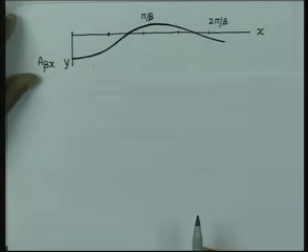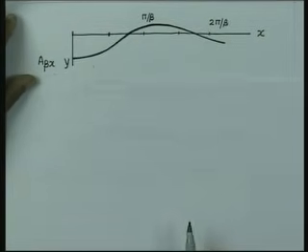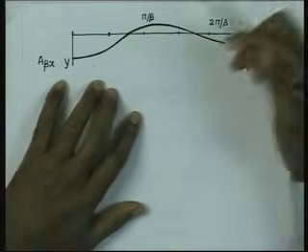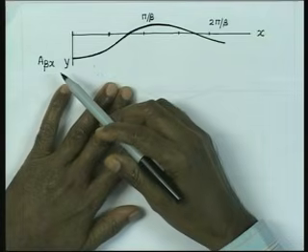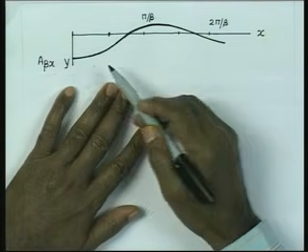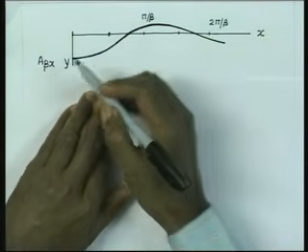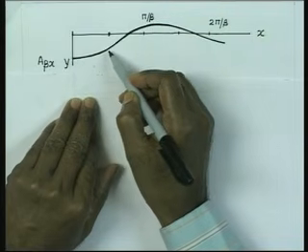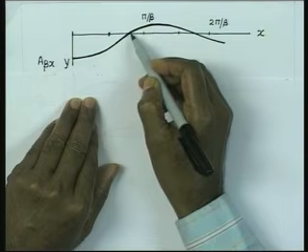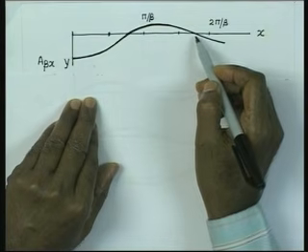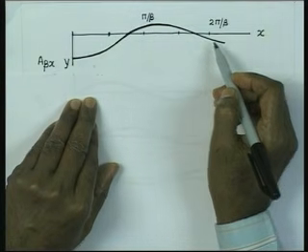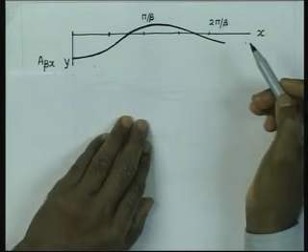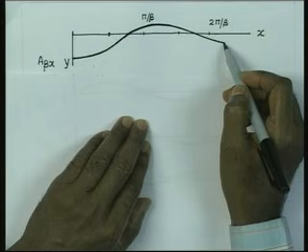So, therefore, if you consider the function y is directly related to A beta x, so the plot of y, so also A beta x, is like this. You expect that there will be large deflection at the point of application of the load, it reduces and then it really tries to lift up the support and then again it goes on decreasing.